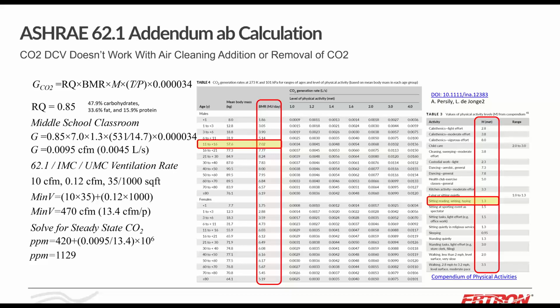However, if you have something that is removing the CO2 in the space with a 30% removal, then the CO2 is going to be reading 790 on your CO2 sensor. And your HVAC system instead is going to think that you are bringing in 25.7 CFM of air when you are not. And if you're trying to control DCV, then your DCV may not even be activated. It may not even move off the minimum setting. It's always good to measure the air and know what you have.